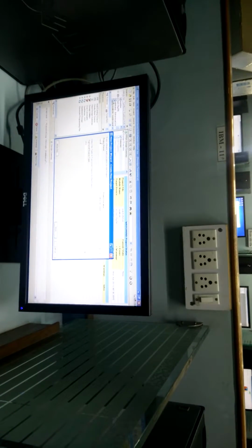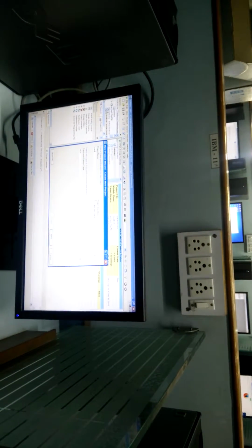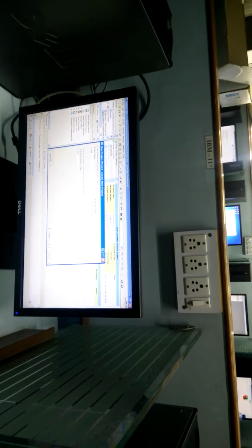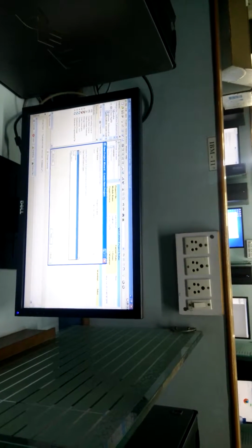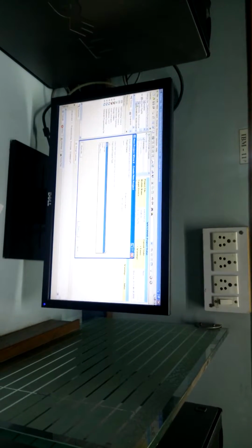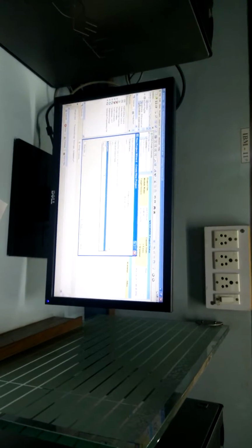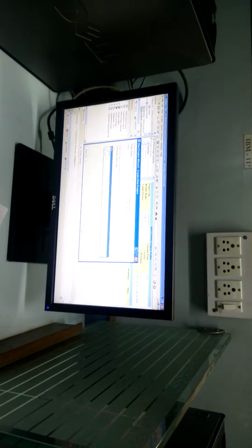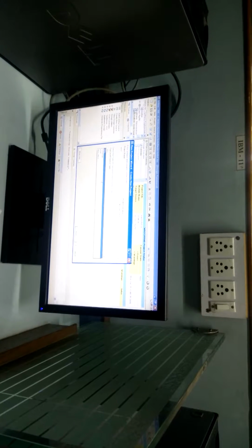After giving the name to your project and deciding the location, go to source type selection. Here the available sources are the ways of design entry. Either you want schematic entry, HDL entry or FSM entry.